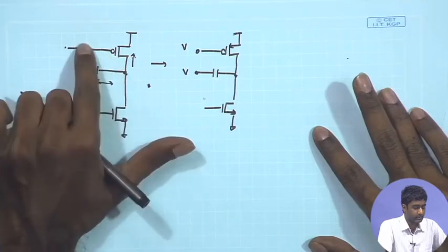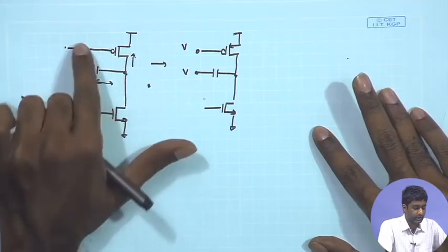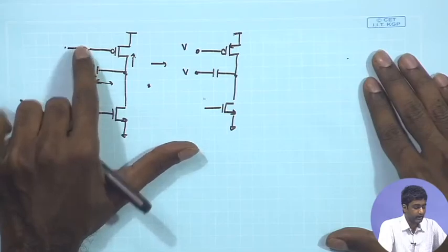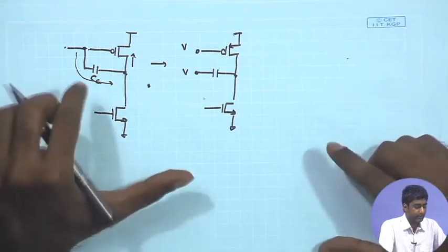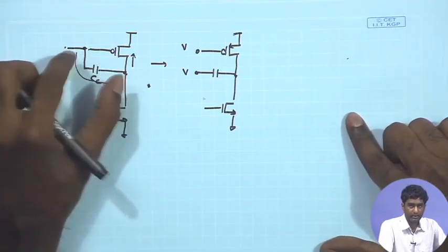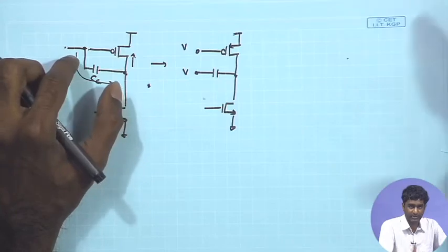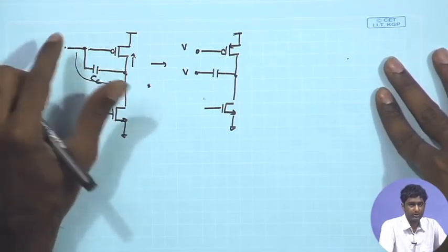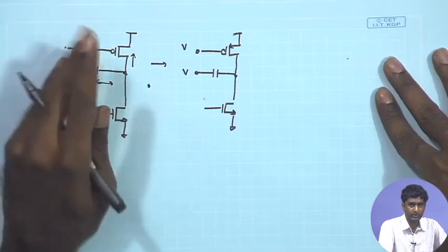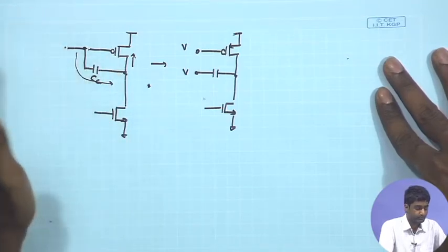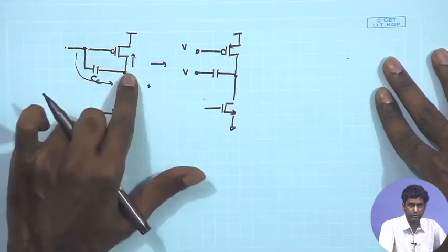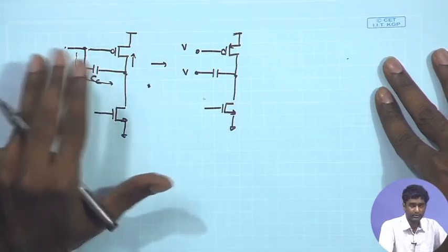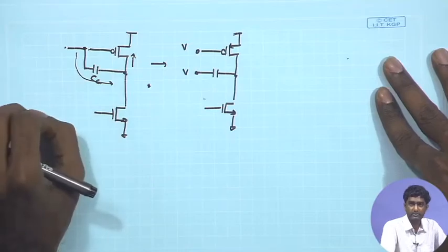So, we are ignoring the signal propagation through these capacitances at higher frequencies, and remember that the concept of Miller effect that we use has an inherent approximation, that the same low frequency gain is valid at higher frequencies at which we are applying those capacitances also, which is not true, because when we apply Miller effect and take the low frequency gain, that is valid for the pass band or low frequencies below the dominant pole of the circuit. As we go towards higher and higher frequency, the gain also reduces, which we do not take into consideration while applying our approximate analysis using Miller effect.